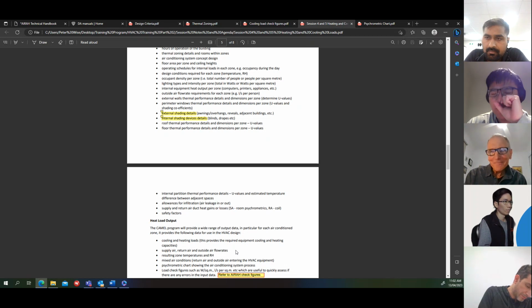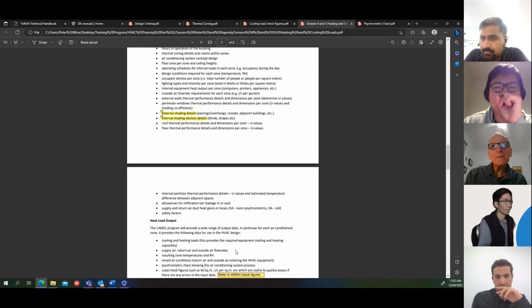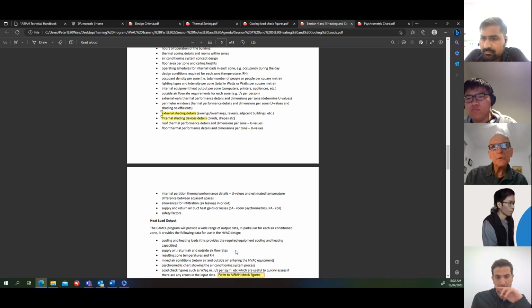Good question. Again, that's a difficult one. There's a few of these things that don't amount to much in the total heat load. So it's not critical, but you do need to put something in there to make allowance for it. I think in a modern building, 0.25 is probably a good number to put in there.